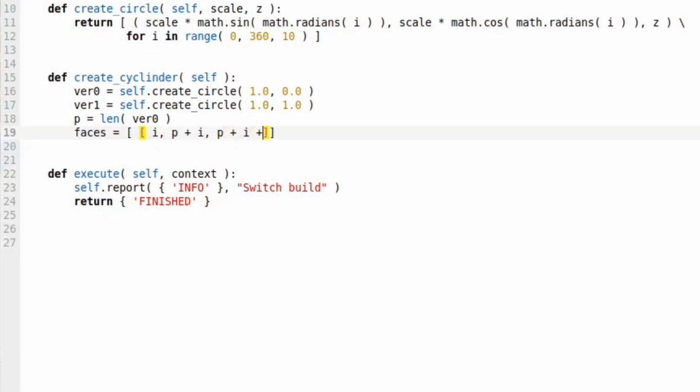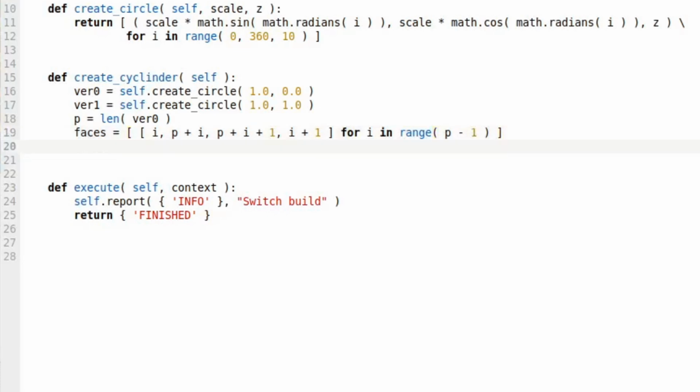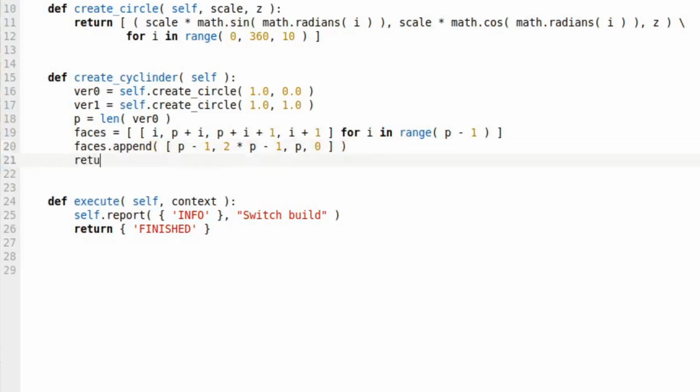The positions of the vertices in the list of vertices are required. The vertices are needed in turn, and always 2 from the lower circle and 2 from the upper circle. At the end you still have to create the face between the beginning and end of the circles. Since there is only one vertices and face list, both are still connected.